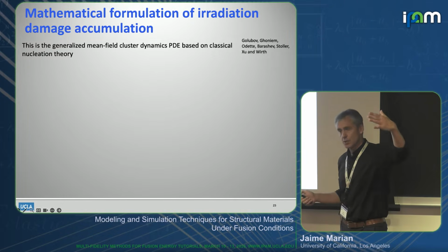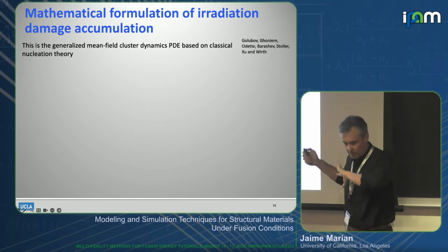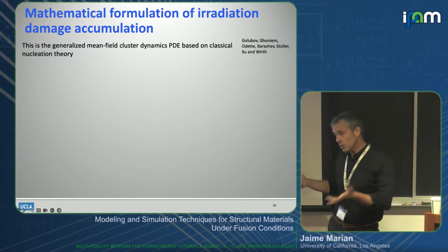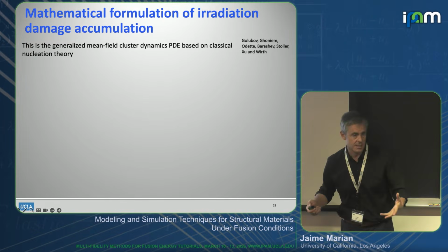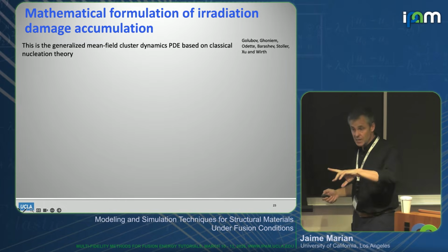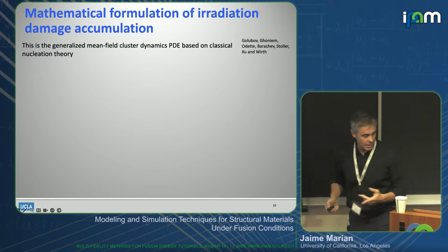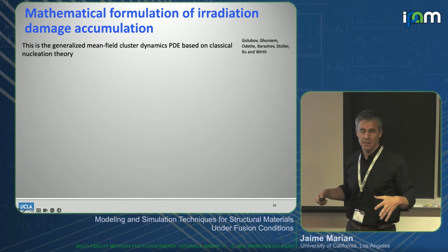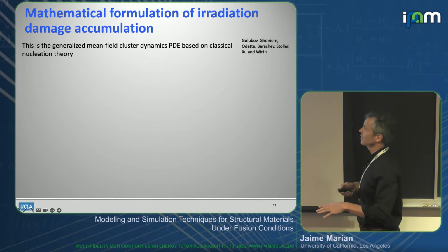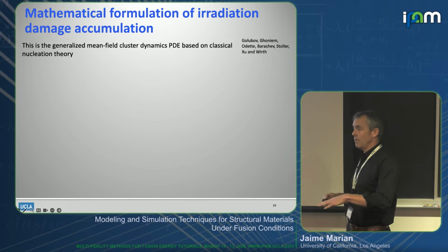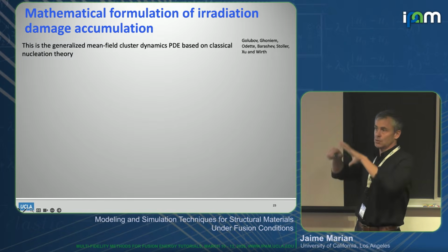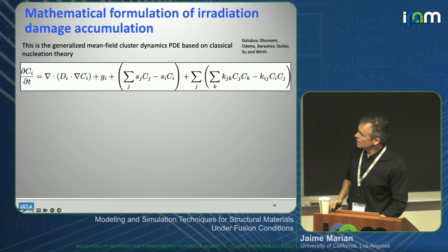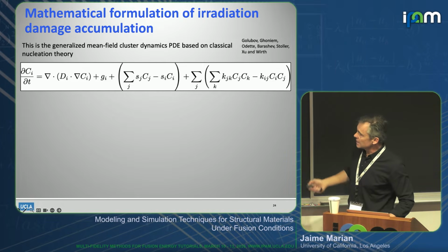We're going to assume that there's an external source of reactants, which is irradiation. You have neutrons or high energy particles coming in. They're producing a bunch of species. They're not really chemical species, they're structural species like defects, vacancies, self-interstitials. Through transmutation, you may introduce new chemical species as well. And now those species are all reacting with one another, everybody with everybody, and they're reacting with the microstructure, and they're subjected to the boundary conditions, just like a standard chemical reactor.